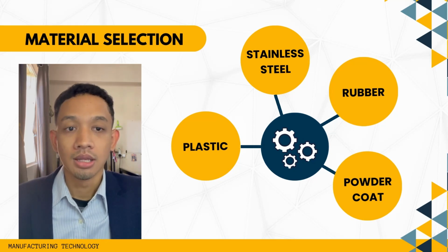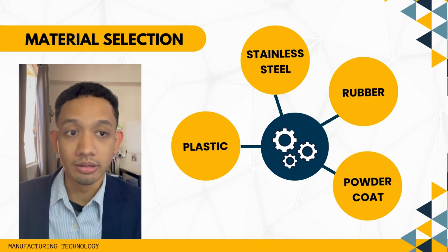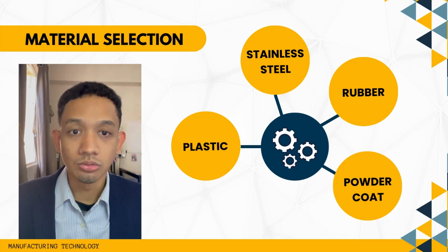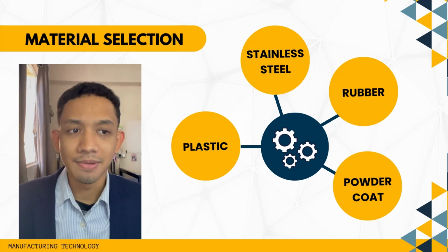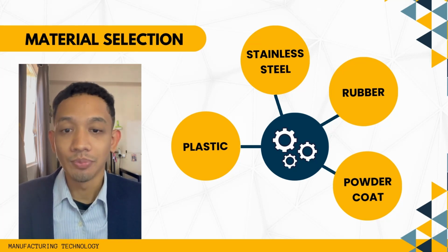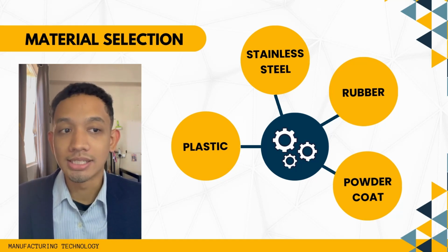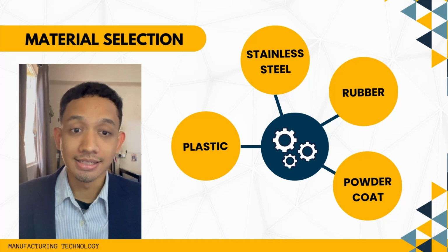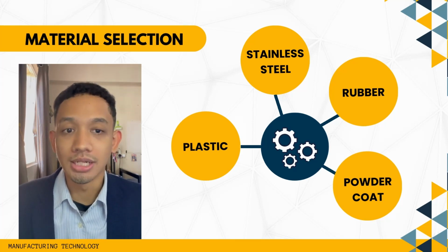Next is powder coat, and the MCB box will be painted with powder coating to ensure the box is durable when confronting really bad weather. And the powder coat, similar to stainless steel in nature, is corrosion resistant. Being corrosion resistant is especially important during outdoor installations where the exposure to elements that can lead to corrosion is high. And aside from that, powder coating also allows for better durability due to its tough finish. It is resistant to chipping, scratching or fading, making it a perfect combo when producing a long usage product.